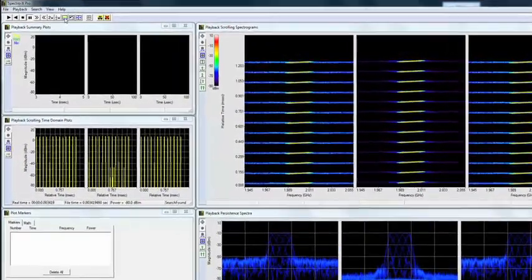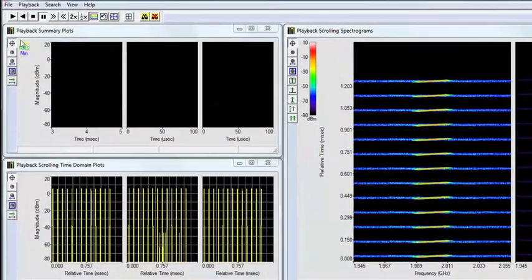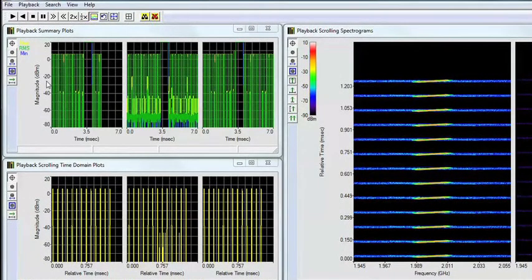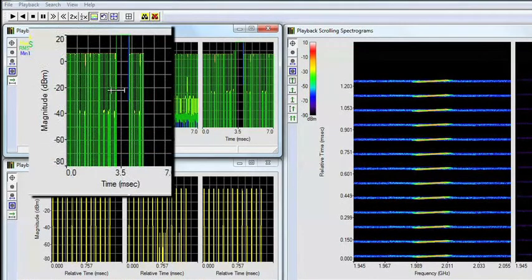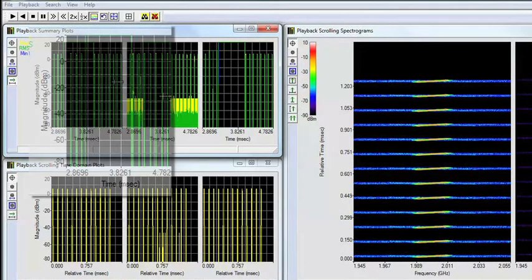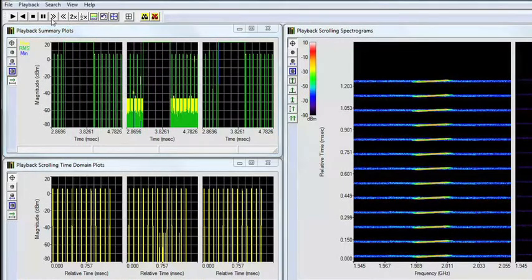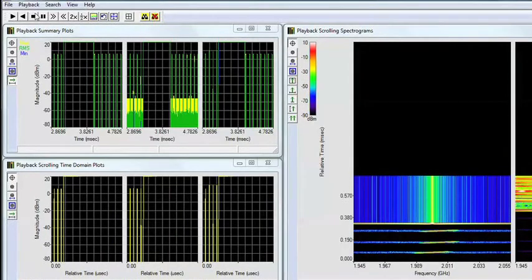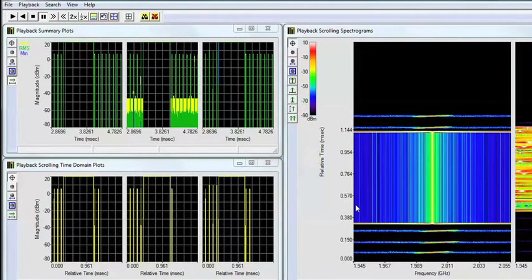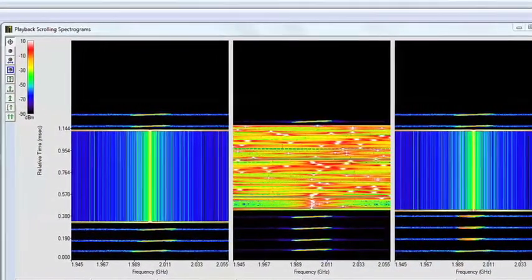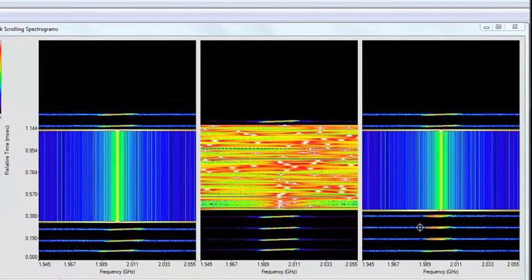If I knew, for example, using the playback summary plot, that there was a particular area of interest that I wanted to begin the synchronized playback with, I could look at the playback summary using the Start From Here tool, tell Spectro-X to only begin playing from where I'm gesturing in one of the windows, release that, and then begin the play from that point of view, getting much more quickly to what perhaps is an area of interest across all 3 channels.